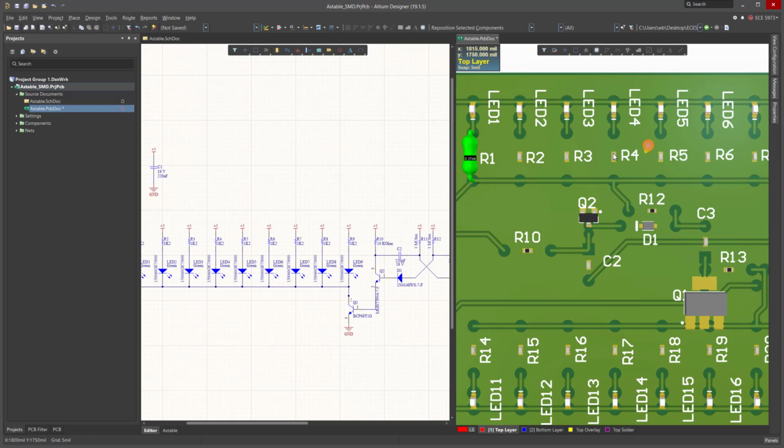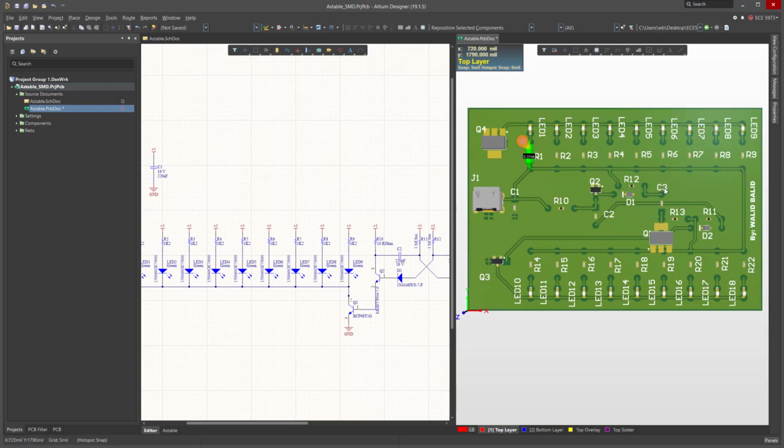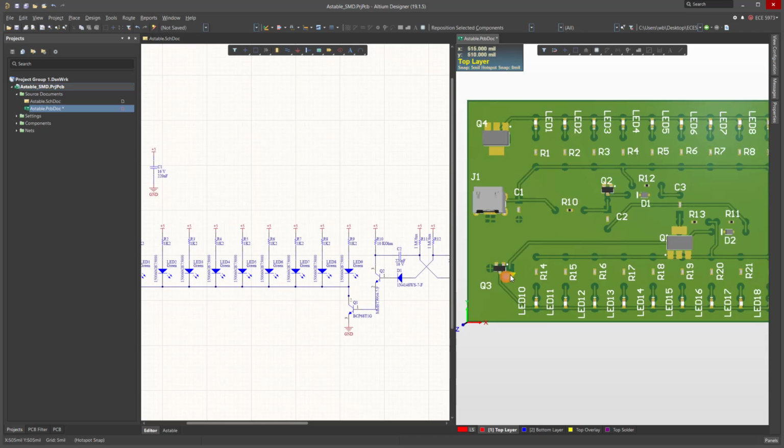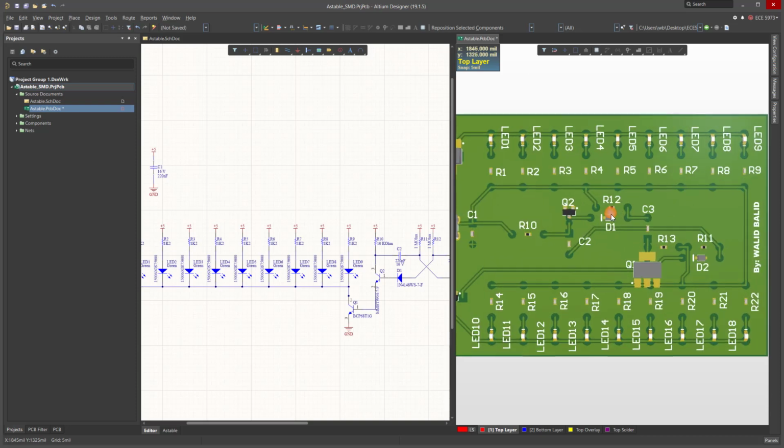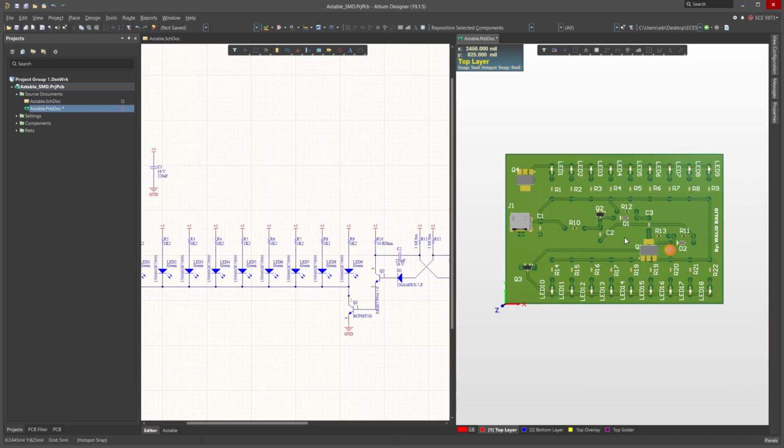Remember, we had through-hole resistors in here and also in here. Let's remove this 3D model because this was the old one. Look how much the size is different now. So resistors, transistors. So this one and this one are the switching transistors. These are the load transistors in here, and we have the diodes. They are small, and now we can reduce the size of this board significantly.